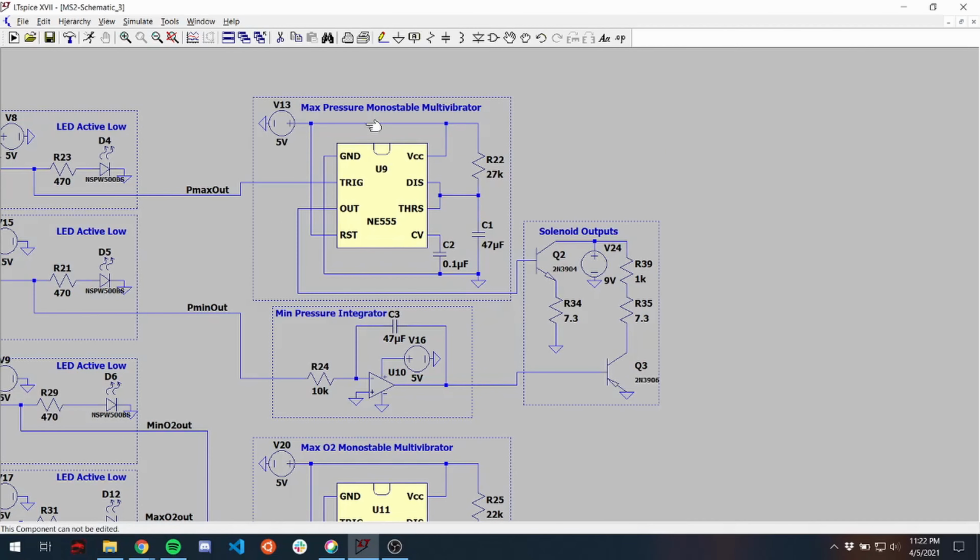The reason for having a monostable circuit combined with an integrator circuit like this is that, let's say we use 2 monostable circuits instead, we could end up just bouncing back and forth endlessly, given a large enough time constant here. Because if we're talking about pressure, we're just saying we're going to release pressure, we're going to add pressure, but we have no control over the rate at which pressure is being changed. So there's no guarantee that we won't actually get into the region we want.